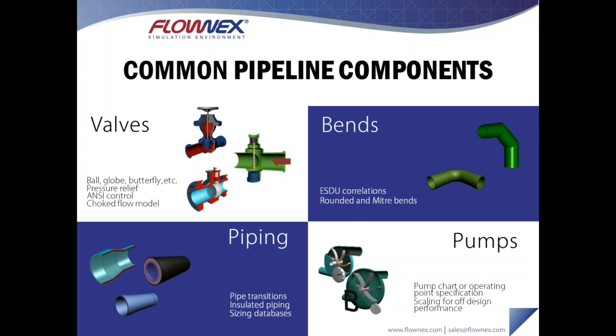In this scenario, you simply specify some basic geometry for the valve and then choose a characteristic for it, be it a linear valve or perhaps an equal percentage valve. And then Flownex uses the relevant theory to model the pressure loss behavior through that component. All of our valve models, along with our flow components, also take choking into account, so that you can also consider that when designing the flow inside of your system.